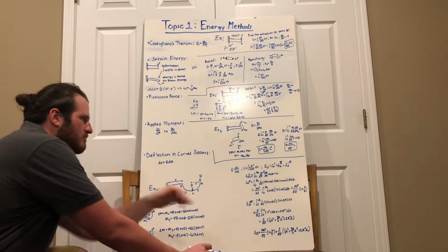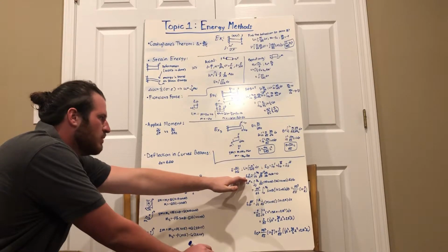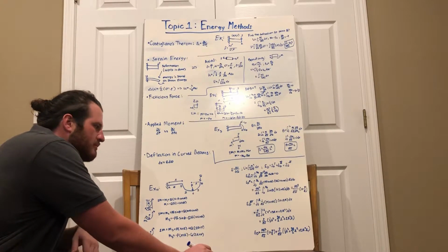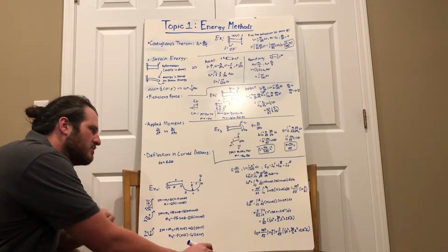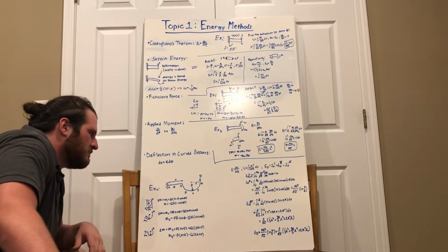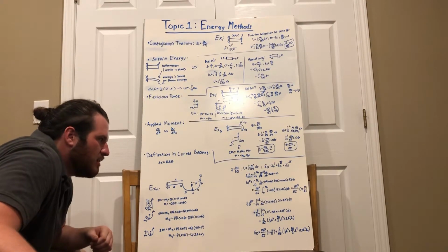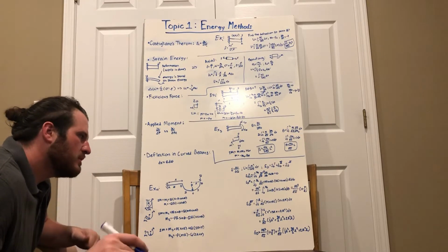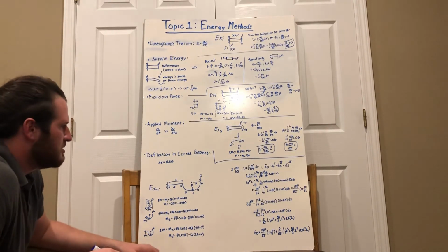Now how do we get to our final deformation? Remember this equation? We apply everything in here together and add them up. Our delta D1 is 0, so we can neglect it. Our delta D2 is PR cubed over EI times 1 plus pi over 4, and our delta D3 is P over EI times 1/3 L cubed and so on. Adding them up, our total deformation is PR cubed over EI times 1 plus pi over 4, plus P over EI times 1/3 L cubed plus 3r over 2 L squared plus 2r squared times L.